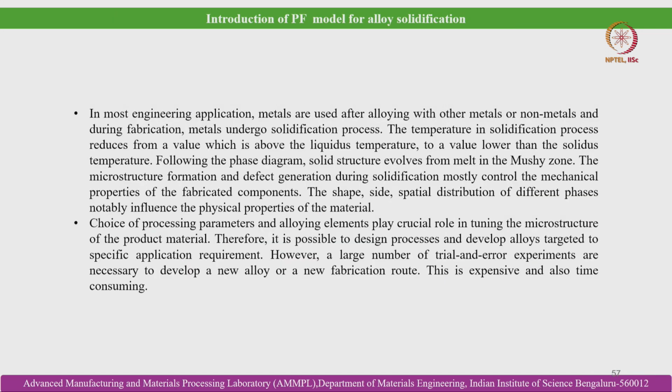Okay. So, let us discuss the phase field model in a little bit of detail. Like in most engineering applications, metals are used after alloying with other metals or non-metals, and during fabrication metals undergo a solidification process. So, the temperature in the solidification process reduces from a value above the liquidus temperature to a value lower than the solidus temperature, if we are talking about an alloy, whereas in case of a pure metal the liquidus and solidus temperatures are the same, and it is signified as the equilibrium melting temperature.